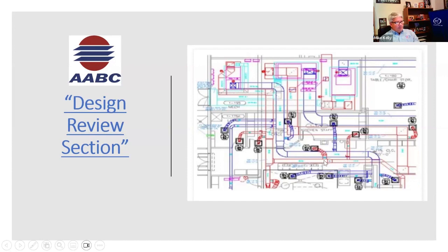Are they in transitions, just after transitions, at elbows? Sometimes you have an end of duct that comes down and goes out, and it goes from square to round immediately, and there's no shown volume damper because it's not a seal tight or an immediate connection with a volume damper in it with a duct takeoff, but it's a transition piece going from square duct to round duct at the end. And a lot of times those dampers get missed. That should get caught on a design review.